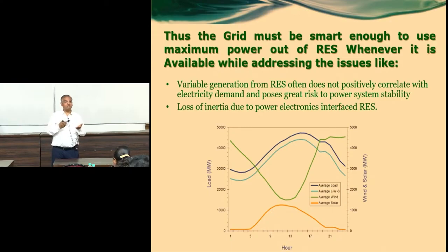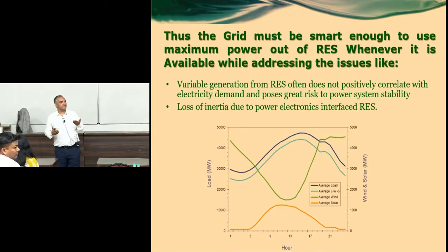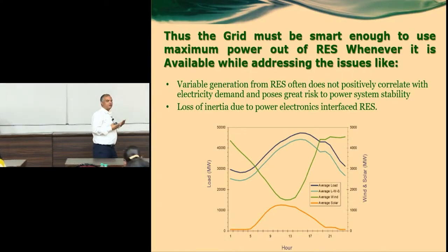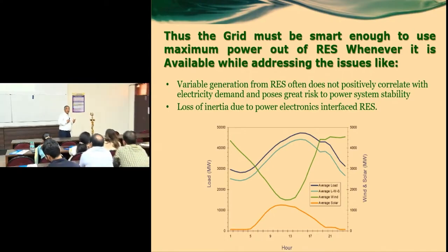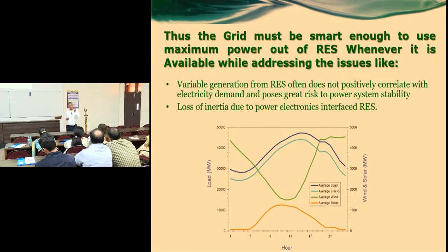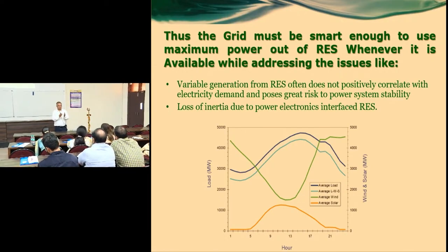The concept is there, 1.6 hour to 4 hour. Why? They have to store in a battery energy storage device. Now integrated projects are coming where, with the solar power plant, you also have to have battery energy storage capability, 20 to 30% capacity. Standards are coming, not very precisely yet, but I know in advance that 1.6 hour is the minimum standard which NREL in the US has decided, and it can go up to 4 hours in the Indian context.